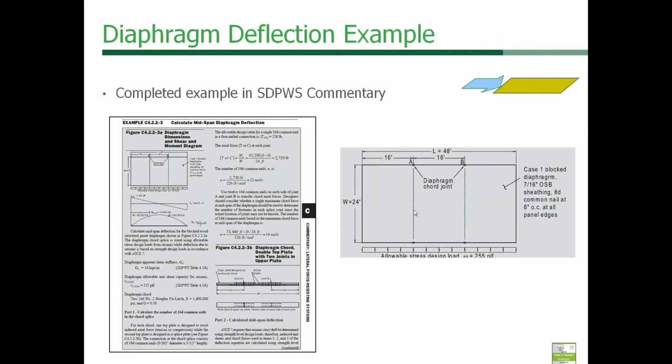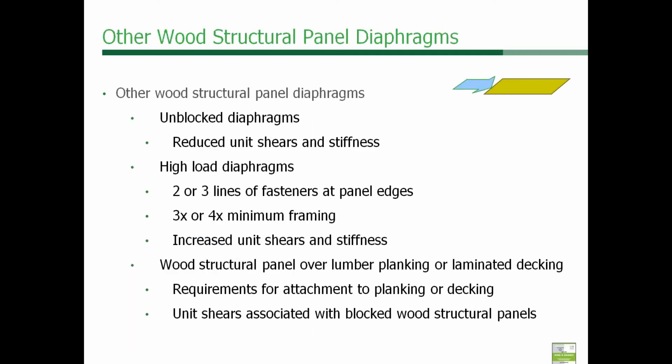There is a complete example for calculating diaphragm deflection in the wind and seismic commentary, and I think we've got an old webinar up on our website under the self-directed study program on this as well, if you want some more information on diaphragm deflection examples. Other things about diaphragms, we do have provisions or tabulated values for unblocked diaphragms with reduced shear and stiffness values. We've got values for high load diaphragms with increased unit shears and stiffnesses.